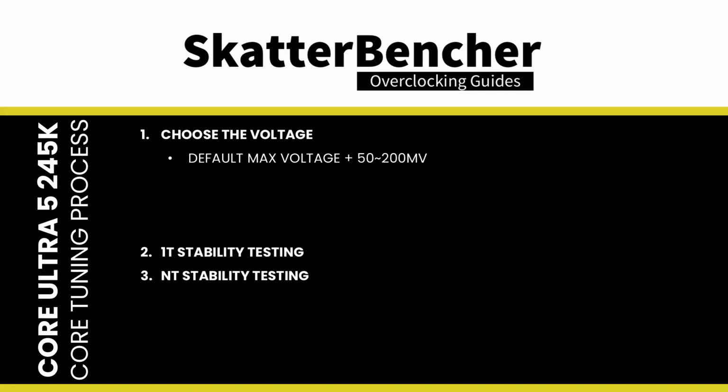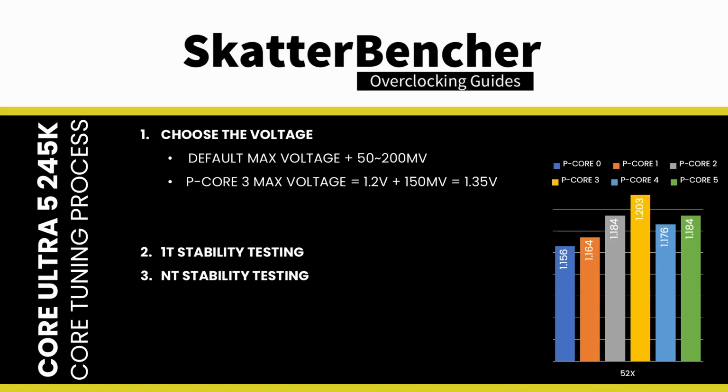The easiest way I find to determine what kind of an adaptive voltage I want to run is basically looking at what's the stock maximum voltage and then adding anywhere between 50 and 200 millivolt. For example, the default maximum voltage for this CPU is 1.2 volt for P-core 3, so I decided to add 150 millivolt headroom and set the P-core adaptive voltage to 1.35 volt.